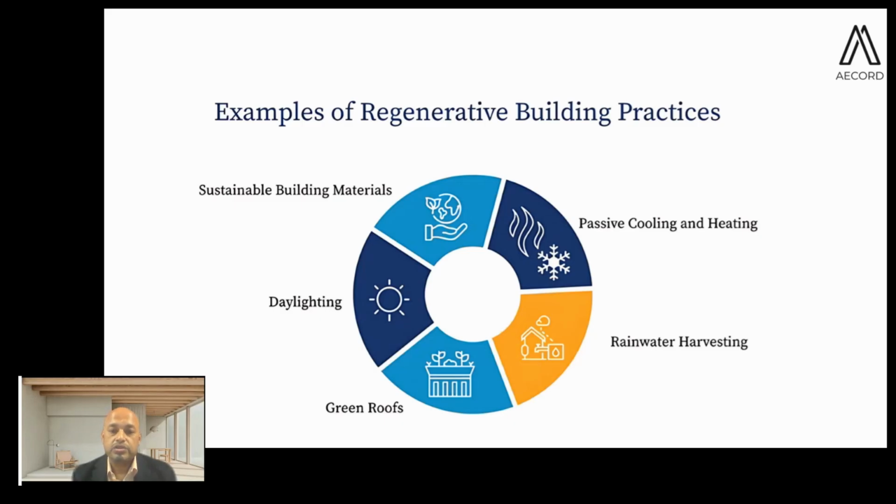So if you just go with a ventilation system, or passive ventilation systems like a solar chimney, the stack effect, as we call it, or something called PDEC, passive downdraft evaporative cooling. So in arid climates, you may go for passive cooling, and in cold climates, you may go for passive heating. How much time in a year you can really depend on passive cooling and passive heating can dictate your energy consumption of the building being 40 to 60% lesser than your conventional air conditioned building.